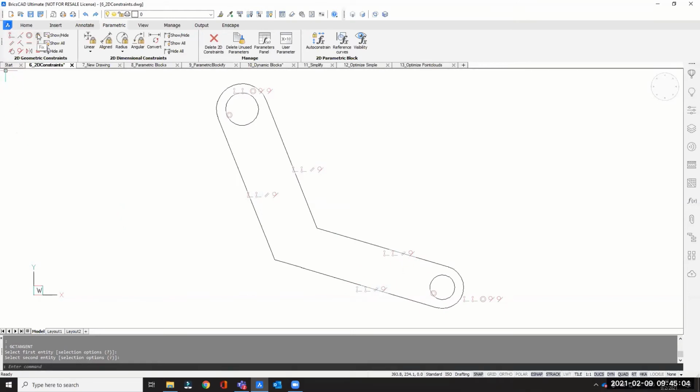Now let's move on and have a fixed constraint here. This is the lock icon here on the 2D geometry constraints side of your ribbon. Using this, let's snap to the bottom left angle of our drawing. It's in here, and you see there's a lock button there. Now if you remember, our goal is to have that finished completed exercise image, which has a vertical and horizontal orientation. So I want to make sure that I have these two lines always in vertical.